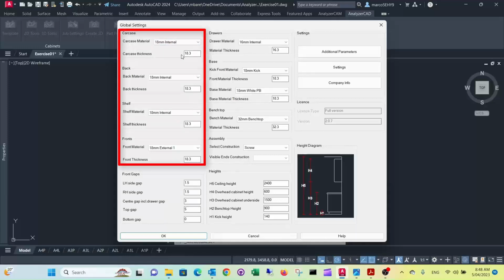We generally go slightly over: if you use an 18mm board, we go to 18.3. The reason for that is that there is a tolerance in a board. Quite often boards can be up to 0.3mm thicker. So we really don't want to have our cupboards to grow. So we allow for the highest possible tolerance, and that works out quite well.